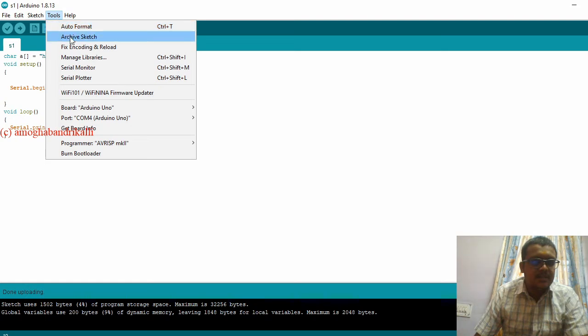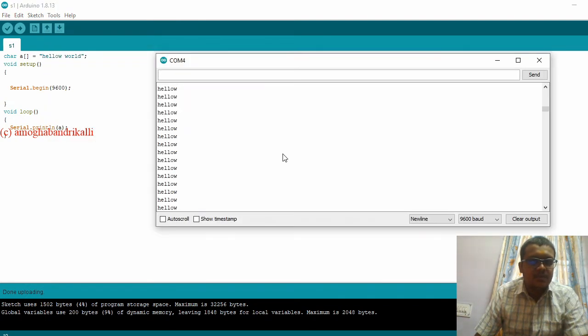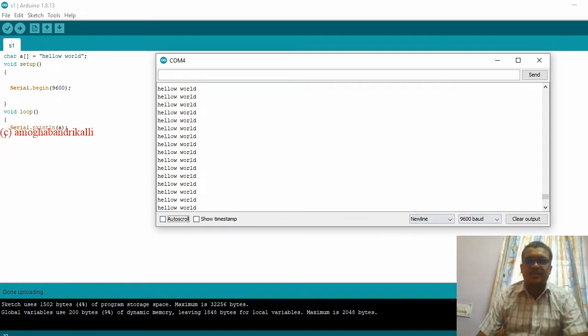Okay, you can just see this in the serial monitor. So you can just see "hello world" is going to be continuously displayed. And also it is having a baud rate of 9600. So these are all the changes you can just make.